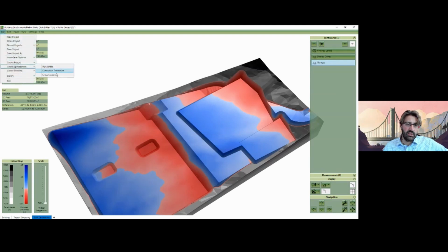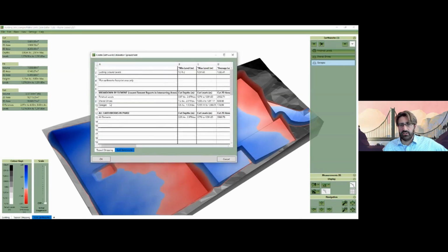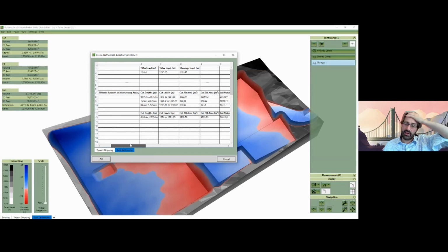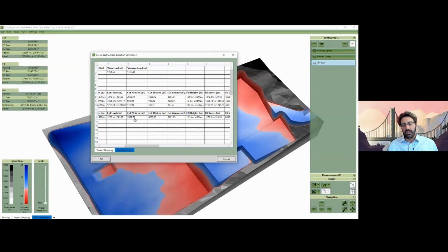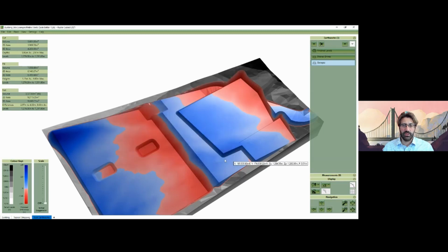So without further ado, I'll try and do this earthworks estimation. So we've got the finished levels, we've got the shared drives, and we've got the garages broken down by region, even though they're intersecting. It seems like a small thing, but that really is a big problem when you've got a big housing estate with say 50 houses or something like that, or 150 houses, and it's a lot of work to just get it to calculate cut and fill, and then it's a huge amount more work to try and get it to break down in a more granular fashion. So this is a really important part of the upgrade, even though it doesn't look so fancy. It's quite a powerful new thing.